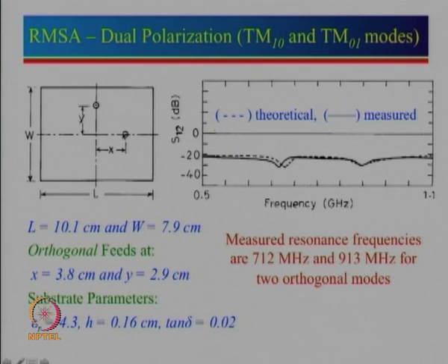So, for this feed point, just for a moment think that y is not there, okay? This feed point is not there. So, if this is only x, then what will happen? It will excite a fundamental mode which is 1,0. So, 1,0 means this will be plus V going to 0 and this will be minus V which is the maximum. So, since this is 0, this entire thing is 0.